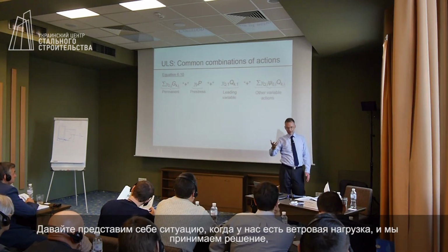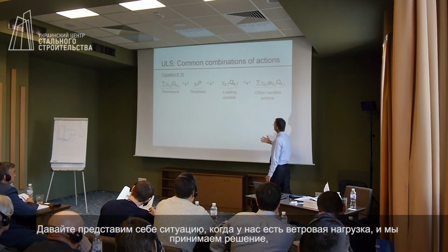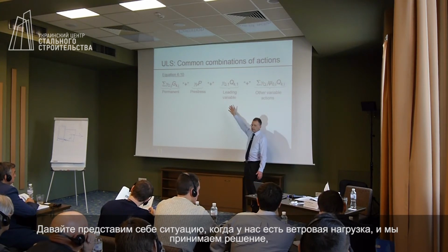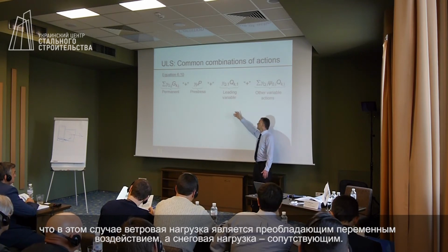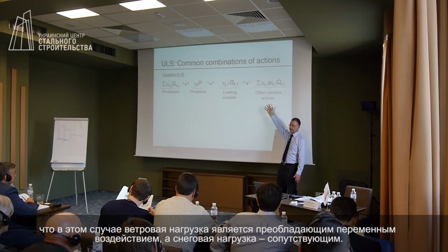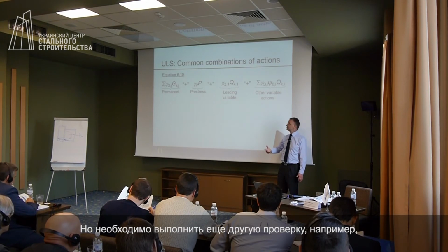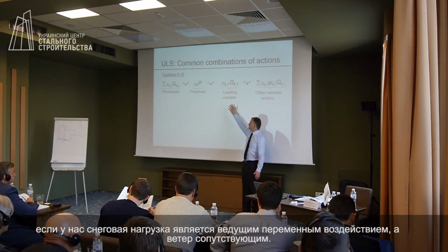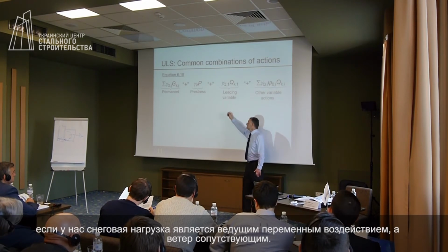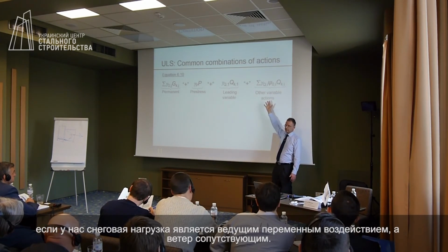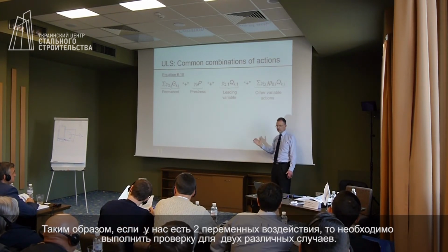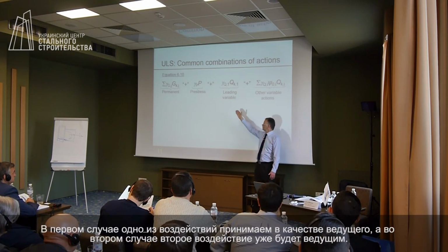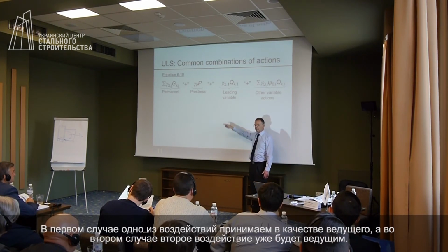So let's imagine then that we have a situation where we've got wind here, and we've decided that in this case wind is the leading variable action, and we've got snow here. There is another condition to check, and that would be snow as the leading variable action and wind here. So if we have two variable actions, there are two situations to check. One of them as the leading variable action, and then the other one as the leading variable action.